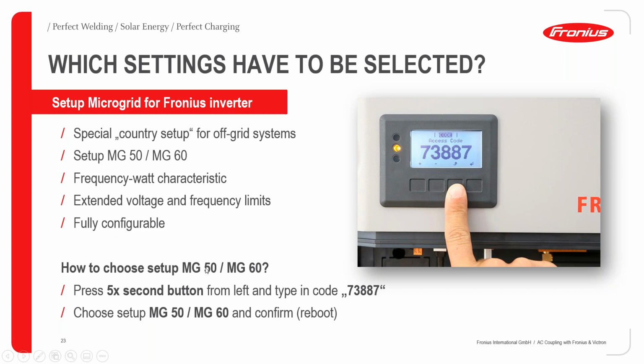And how do you choose this MG50 or MG60? All you need to do is tap this button on the display unit of the Symo inverter, the second from the right, as you can see. If you tap it five times, you would have all these digits in zeros. Then use the plus, minus, and enter buttons to input 73887. That is the access code for the country setup. Once that is done, you can scroll and select MG50.